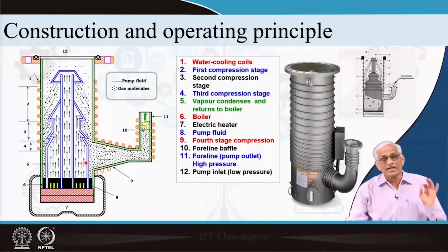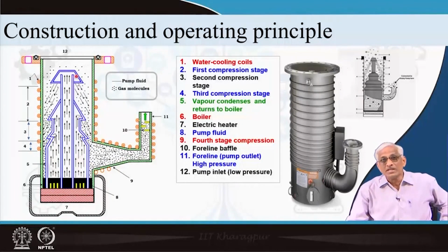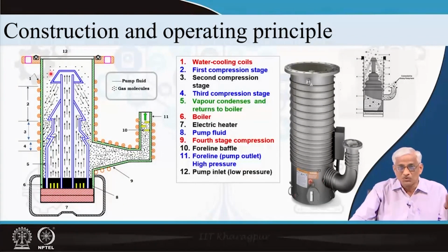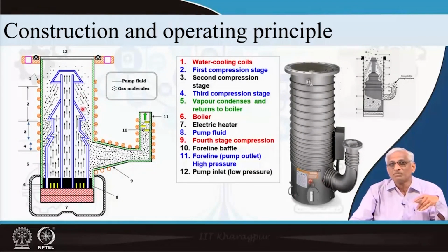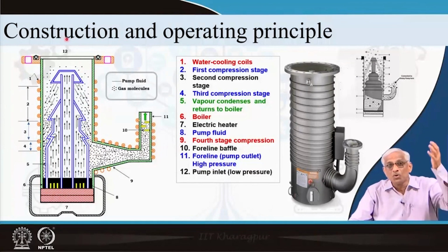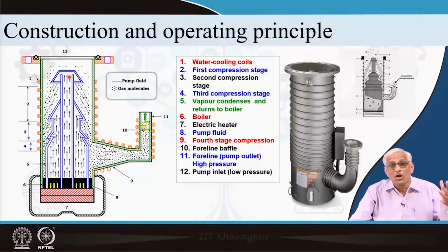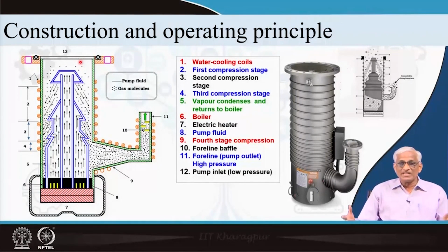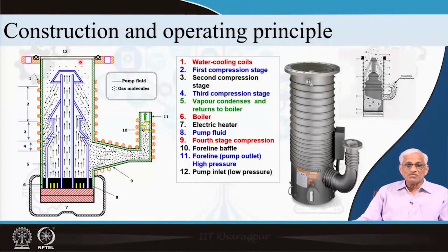At that condition, when you are switching on the heater, these heavy oil molecules, whose molecular weight may be 500, 600, compared to the molecular weights of these gas molecules, which are only 28, 32, will hit them and baffle them down. While doing that, more and more molecules may be arriving, not because of pressure drop, because pressure drop has meaning only in gases when there is a viscous drag. Pressure drop is no more the driving force for molecules to go from one side to the other.